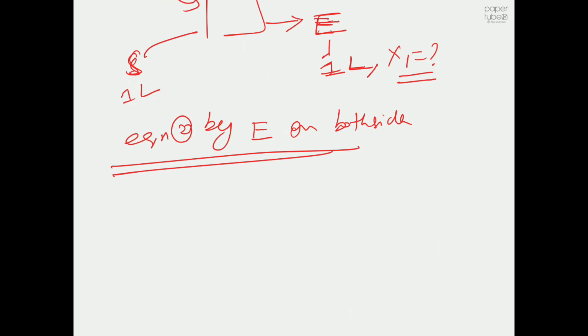So we are trying to eliminate a few parameters so that we can calculate the amount of steroid that we can extract from the solution, based on the distribution coefficient. If you don't know the distribution coefficient, then we cannot solve this problem, or if you have a ternary diagram, then we can solve the problem. But this problem is very simple. We clearly know that this solute and solvent are completely immiscible. So if you know the distribution coefficient, that's more than enough to calculate how much we can extract.